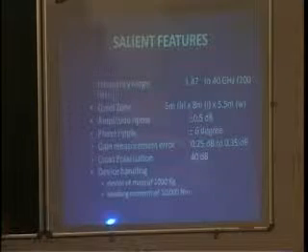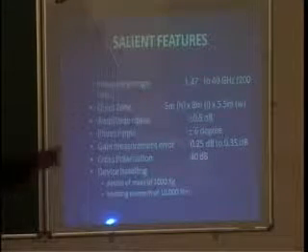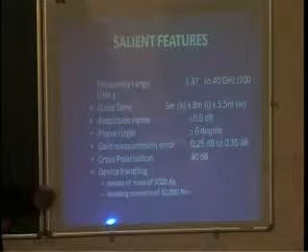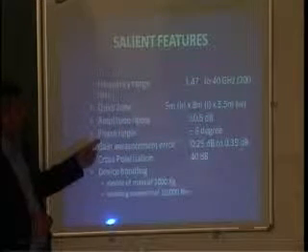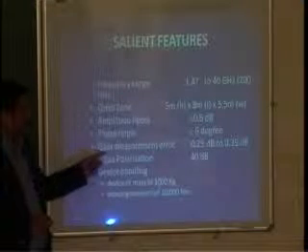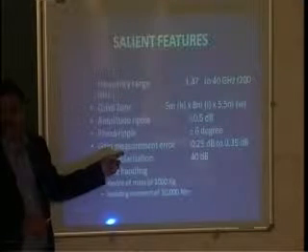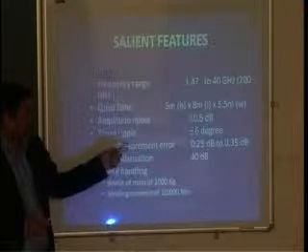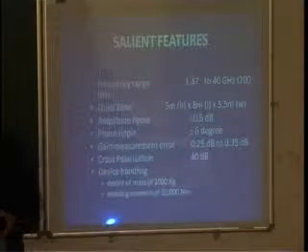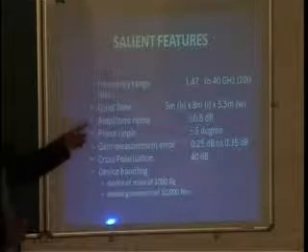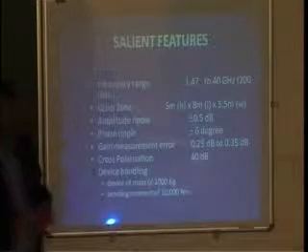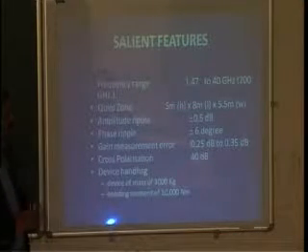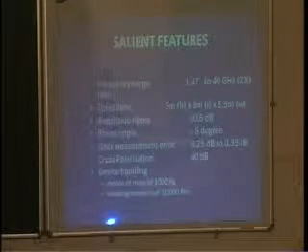We can measure with an amplitude and phase ripple of the order of 0.5 dB and 6 degrees. Now imagine, even with 0.5 dB and phase ripple of 6 degrees, we cannot do the measurement better than 0.25 dB accuracy. Even with 0.25 to 0.35 dB accuracy only, we can do the measurement, even with such phase errors of 8 degrees. And cross polarization, of course, we can measure at 40 dB and better.